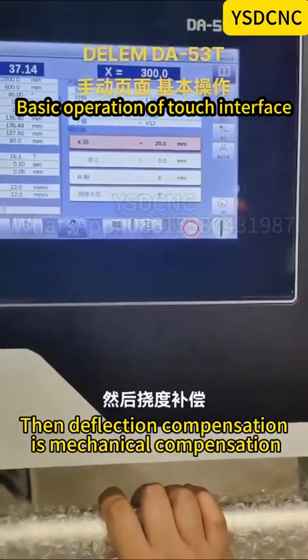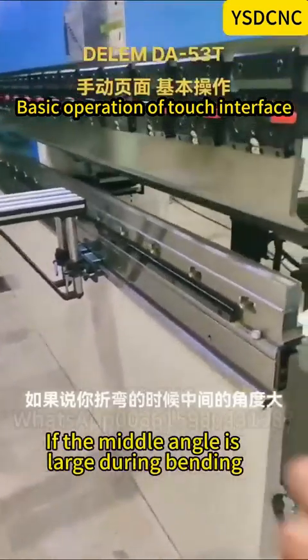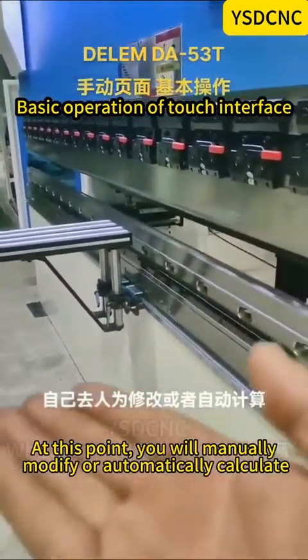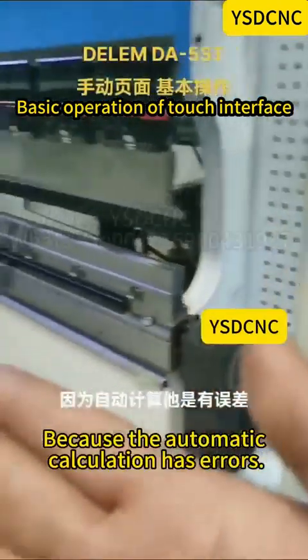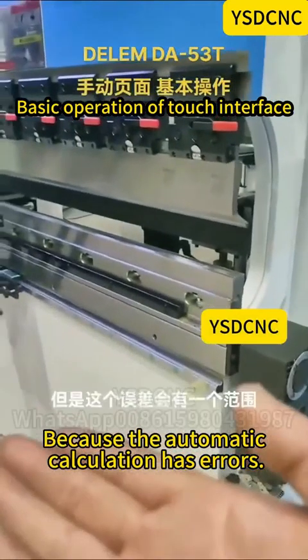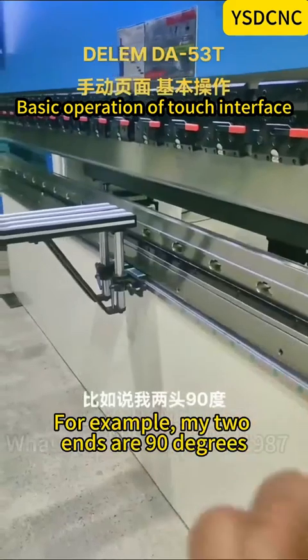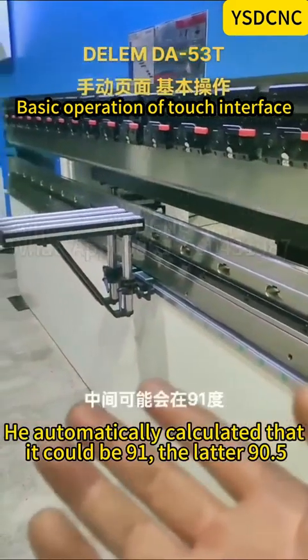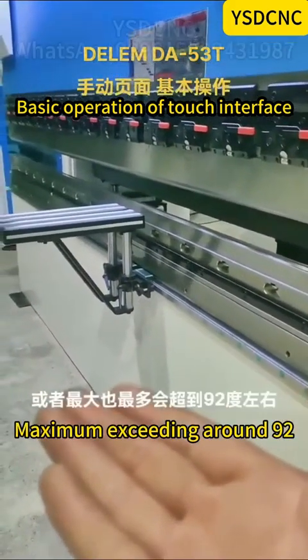Then deflection compensation is mechanical compensation. If the middle angle is large during bending, at this point, you will manually modify or automatically calculate, because the automatic calculation has errors, but this error will have a range. For example, my 2 ends are 90 degrees. It automatically calculated that it could be 91, the latter 90.5, maximum exceeding around 92.